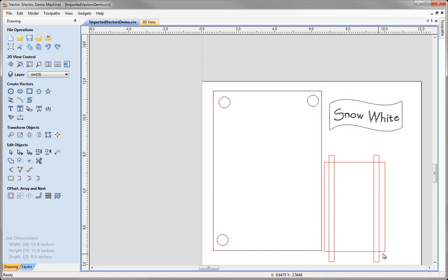Now often the software will correct this problem. If in your vector geometry that you brought in we detect line segments which have common start and end points and which follow each other sequentially in the file structure, then we make the usually safe guess that the data is intended to be a contiguous, closed line, and so the software will often correct these and you won't even notice the error.